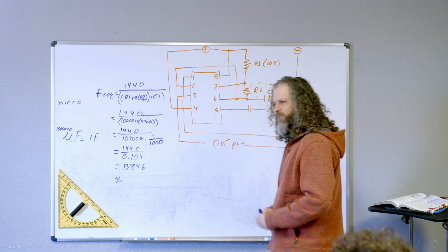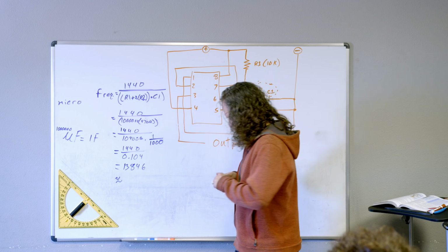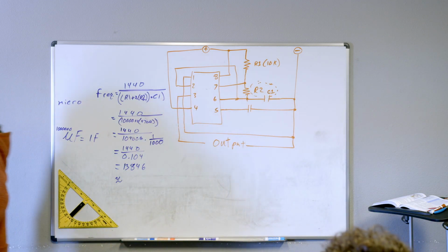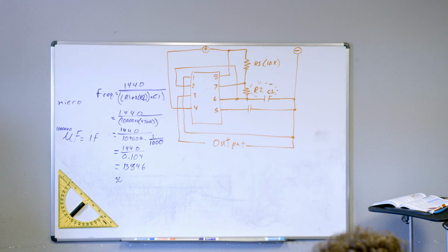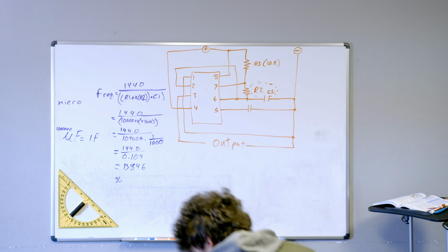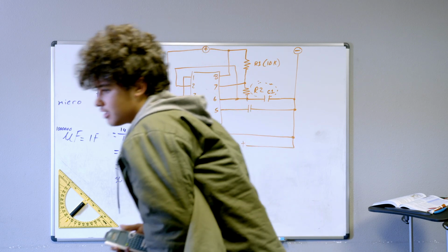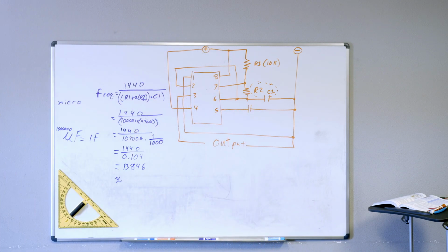Now, what did we calculate? What does it say the frequency is? About 14 a second, 13 a second. No, on the oscilloscope. Oh, there's something weird happening. There's something introduced that's broken it. Uh-oh. Spaghetti. You need to put that capacitor back in there. But it says the frequency is about 14 hertz. So yeah, great. So we got it.